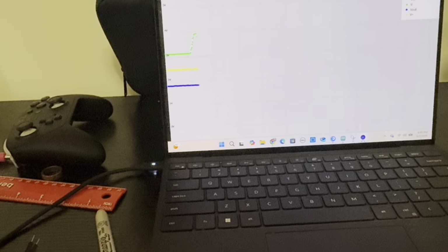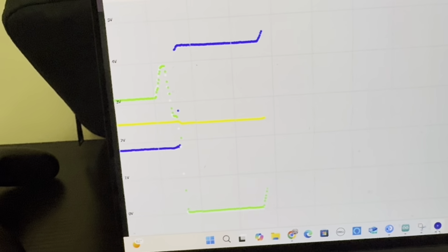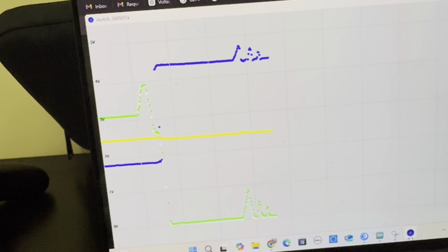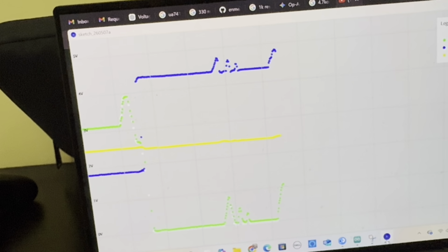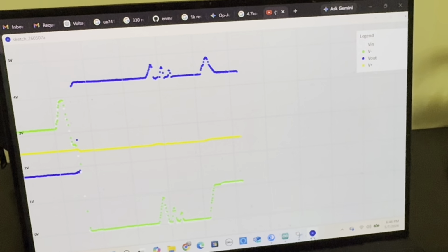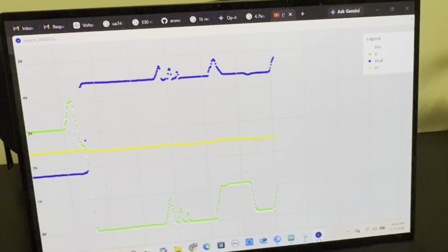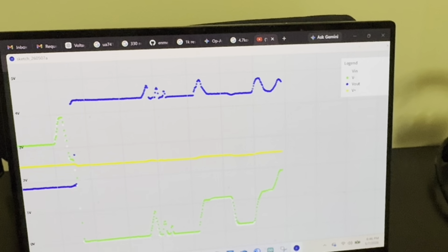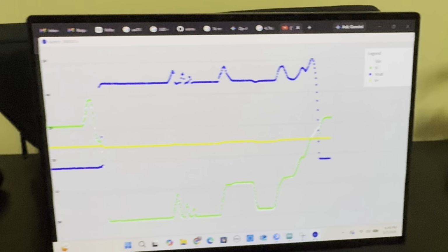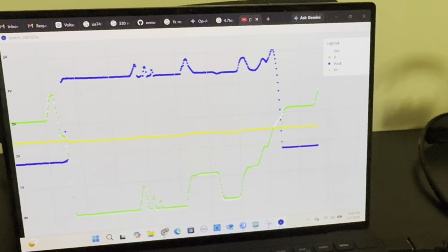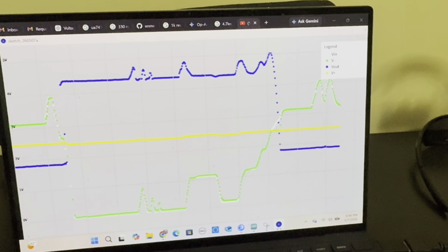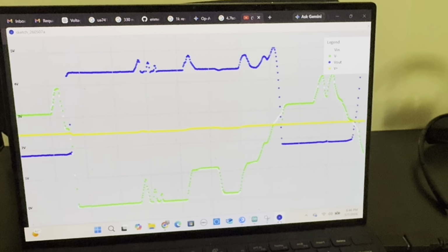Here's my demonstration of my integrating circuit. As you can see, when Vin is 0, Vout is about 4.4. And when you make changes to Vin, it's a similar effect on the Vout, but it slowly goes back to that value. And then when you cross above 2.5, it rapidly drops to about 1.8 volts, and then nothing affects it. And this pretty much lines up with the theory.